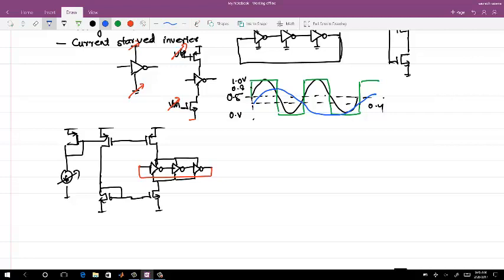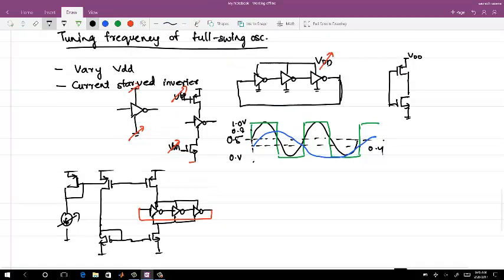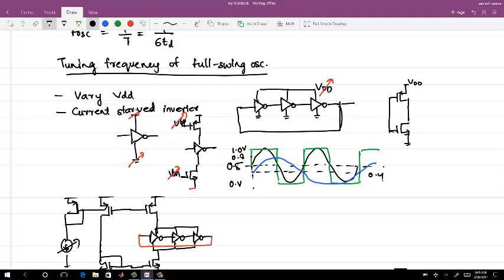So if you are feeding this clock to any other block, and let's say what you normally may do, you take this clock and you couple it with a full scale inverter with respect to VDD and ground. This VDD you do not change, which is always 1 volt. You will see a massive duty cycle distortion at the output. So you never do that. You go and actually put an AC coupling cap.